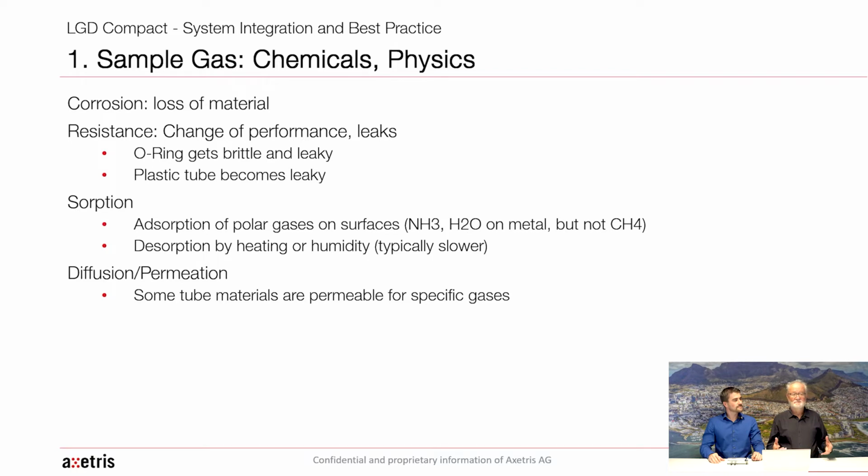So what's happening in our instrument is that when the gas changes from 0 to a span calibration value, like 100 ppm, the molecules will stick first to the walls, and you will not read the value you're expecting. And then the surface is filled, and it will not influence what you read anymore.